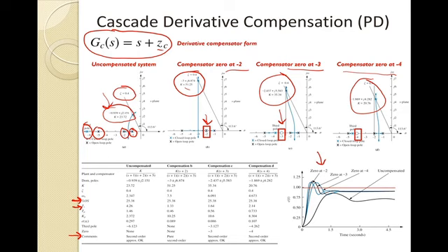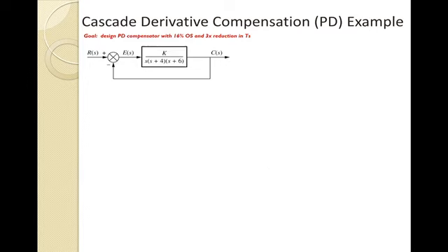Here, finally, you'll see the various plots showing again the faster settling time for all of the compensated systems, and they all have about the same overshoot, which we would expect based on the damping, and overall less steady-state error versus the uncompensated system. But just as we predicted here in the pink, we do have steady-state error relative to this design. Okay? So that's an overview starting point.